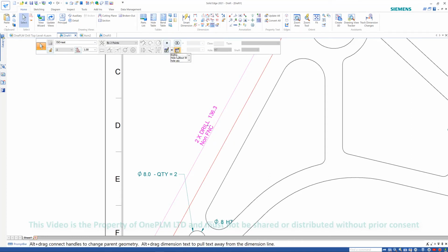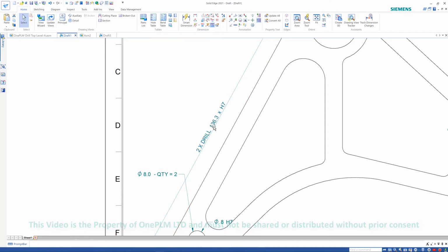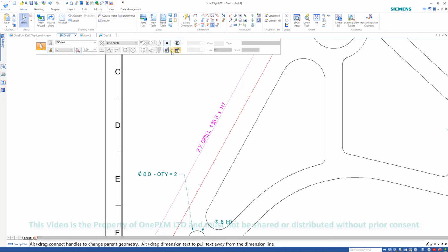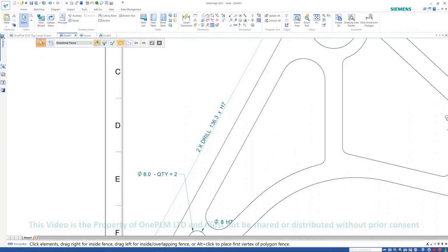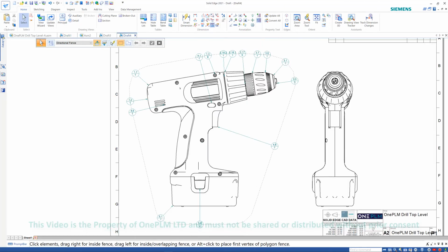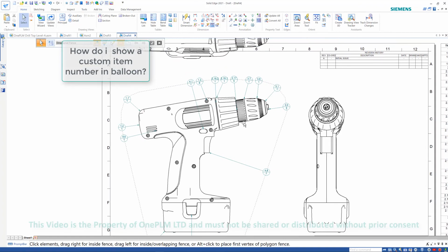There may also be a save setting as well. So we can go in there and choose those save settings. If you've got 10 different notes that you quite often want, go and save those in. Mine doesn't work quite great because I'm on a 4K screen, but if you're on a normal screen, it is a little bit nicer. Again, those save settings are in that reports section. So if you are sharing a server location, make sure you copy the reports folder to your Solid Edge admin folder, etc.